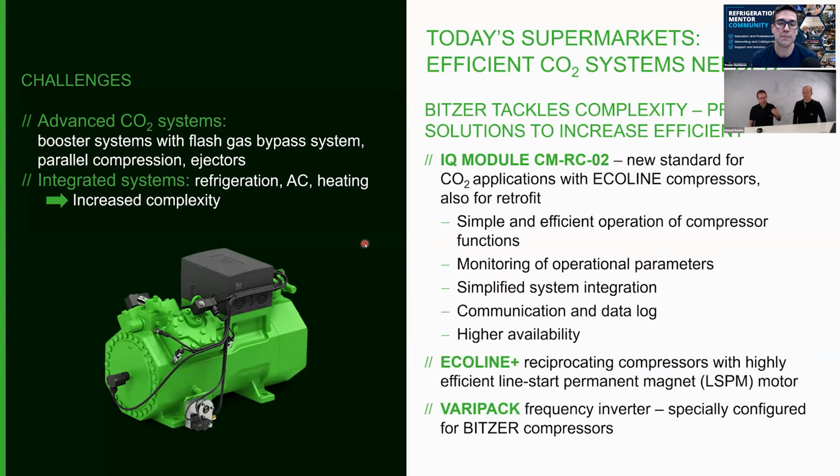We upgraded the system and we investigated the data log after some time of operation. And we found out that the oil injection never called for oil. And we have seen the oil level up to 100%, which means the compressor was really full with oil coming from the suction side.